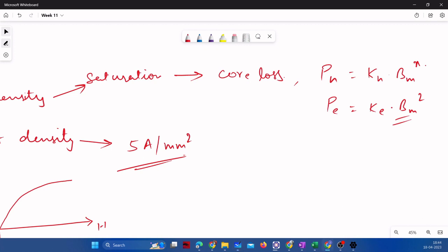Okay? One more advantage of winding this buck type of converter with ferrite, or whatever the material is for the inductor, is that we can wind solid wire with the said AWG or SWG, because we need not consider Litz wire here.